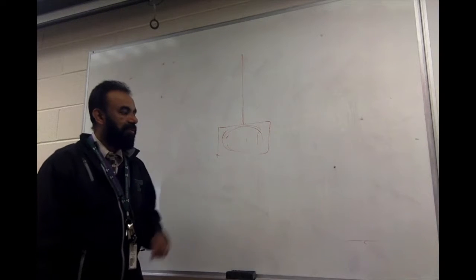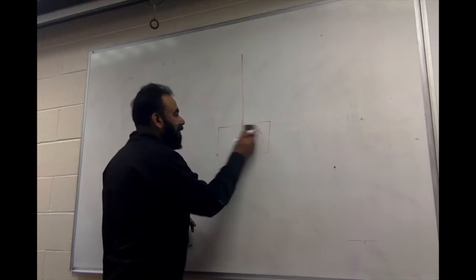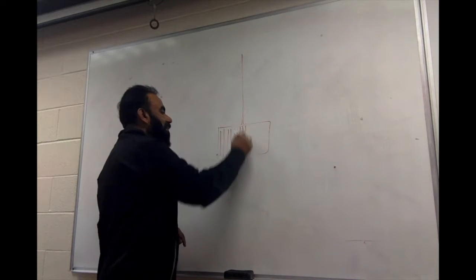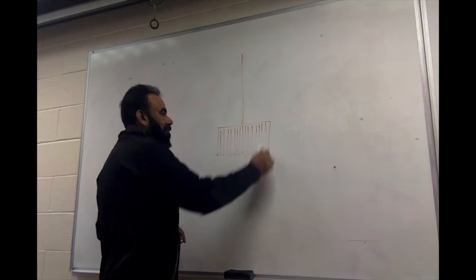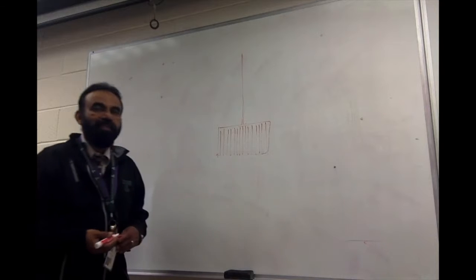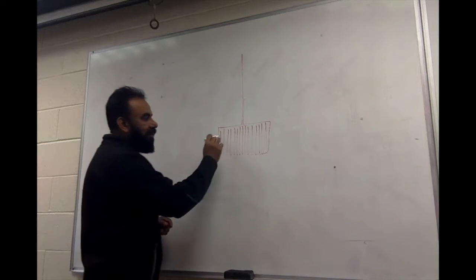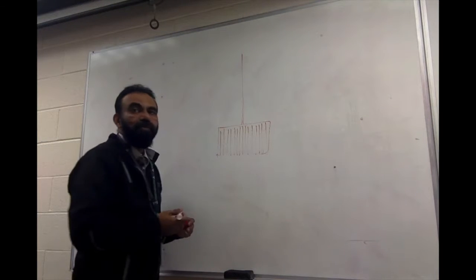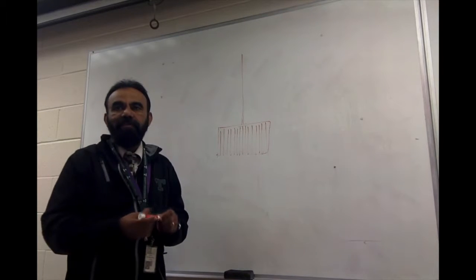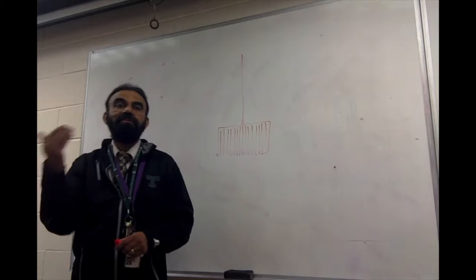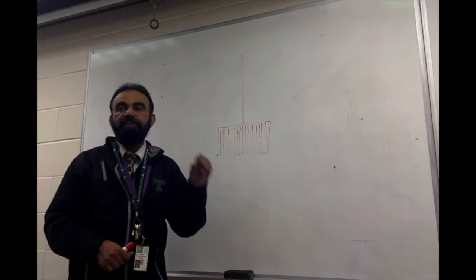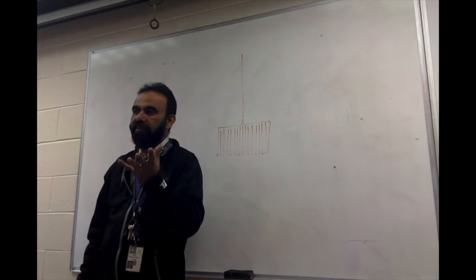And now how do you not let it undergo the suppression? By slicing it as if you're slicing bread. So basically all these are cuts. And when you have cuts like that, you cannot have large-scale currents flowing through them. You can have small currents internally, but they will not cause as much damage as the bigger ones, right? And so this is one way of reducing the eddy current effect.